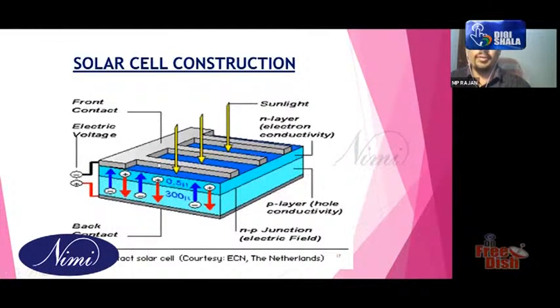Okay, and what is the need for the metal conductor? We will explain it later properly. So this is the electron carrier to the outside. We cannot make a complete sheet like the N-type here because light is needed, so maximum light should fall on this one. So it is called metal fingers. This is called metal fingers.